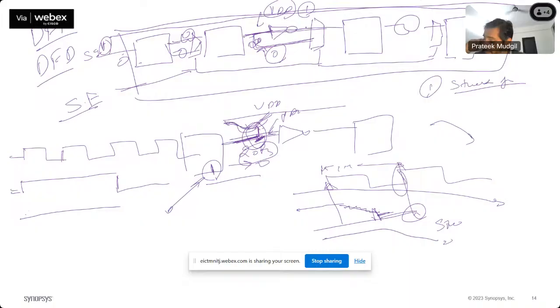So the expectation is that when this 0 0 is there, the inverter will make it 1, so this data will become 1 here. And then again, scan enable will go high, and data will be shifted out, right? So 1 will be shifted out. So 1 after 2 clocks, I will receive a 1, right? But here, if you see, instead of data being received 1, I received 0, right?